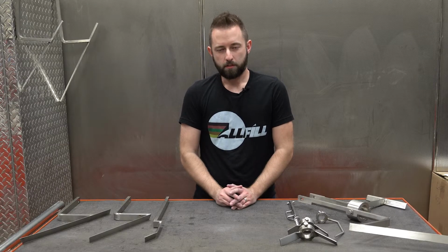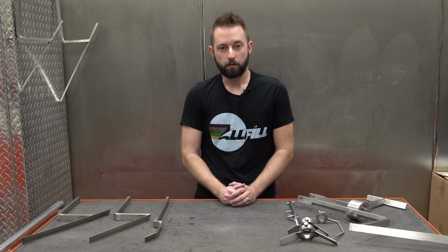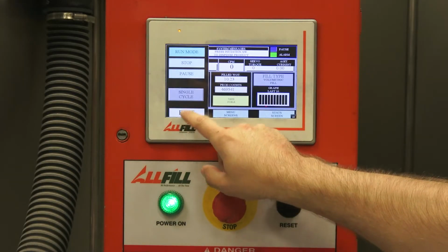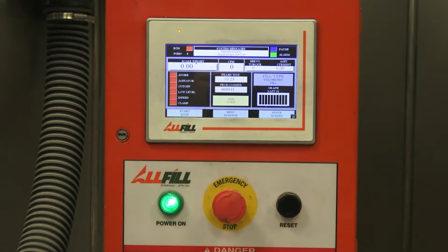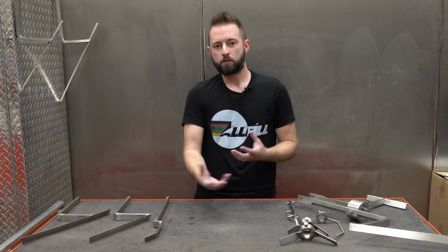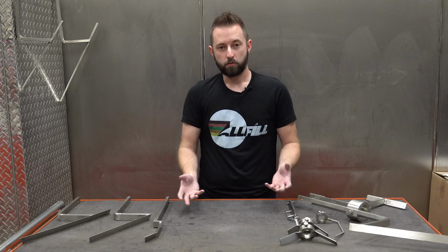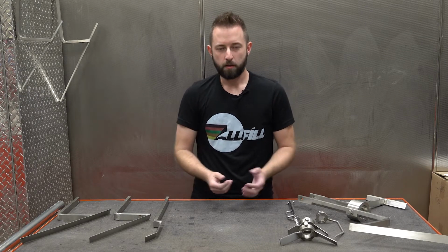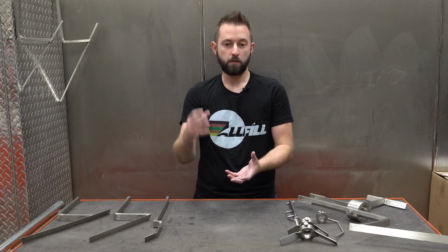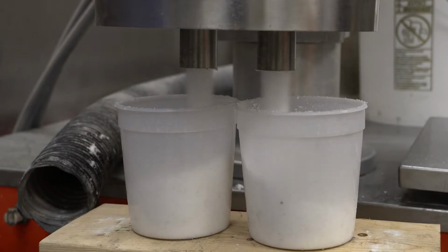The only downside to continuous agitation is that we can have a lot of degradation happen to your product. Because regardless of what's going on, let's say your operator shuts the machine off and goes to take a break, the agitation blade will still be turning. With that, you now have product that's inside of that hopper that can slowly densify because you're making the powder finer, you're damaging granules and different particulates of product. So you can actually have a change in the characteristics of your product, which can change effectively the efficiency of the auger. You deliver more product or less product depending upon how damaged the product is.